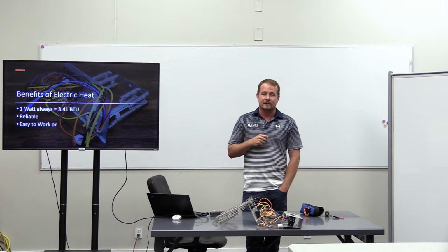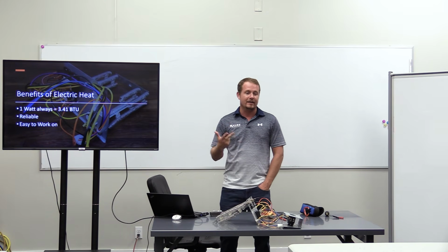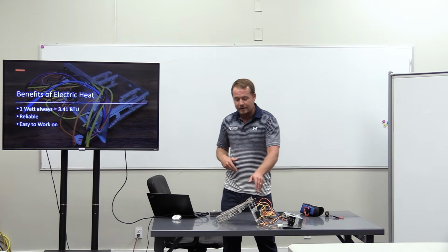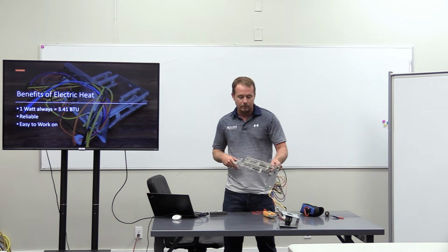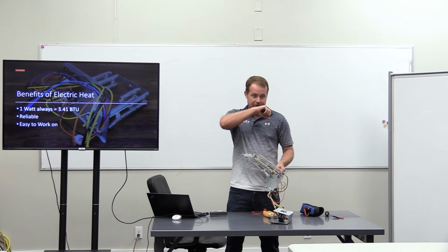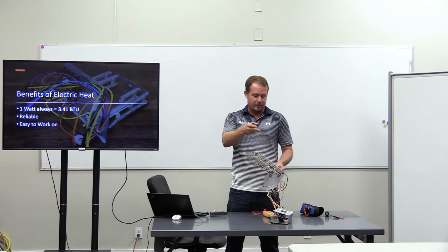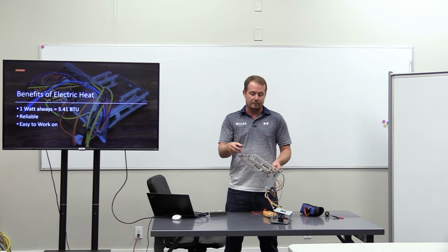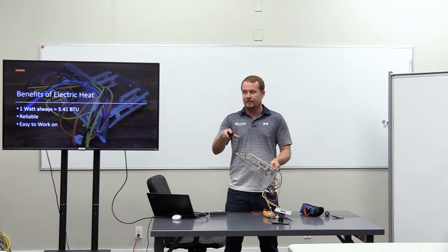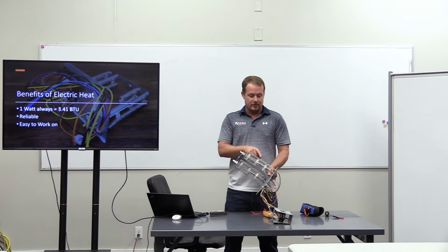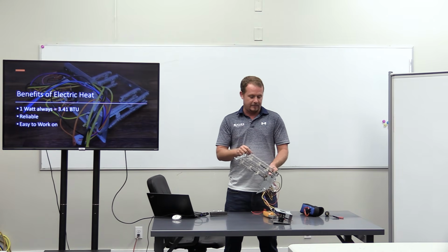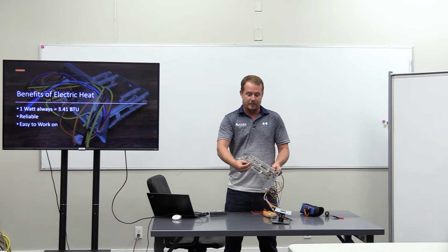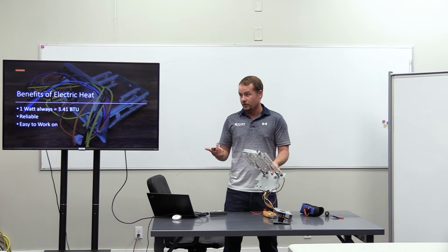Yeah, okay. So I was working on a package unit, and at that time, the company I was working for, they would give us heat restring kits. So they had a failed heat strip. It was shorted out or open or whatever. It was actually burned, and they gave us this kit, a 5 kilowatt heat restring kit. So it had the entire thing. It was in a little plastic bag, and you were supposed to take it and restring this whole thing, put it back on the insulators and all that. That's what we had on our trucks.